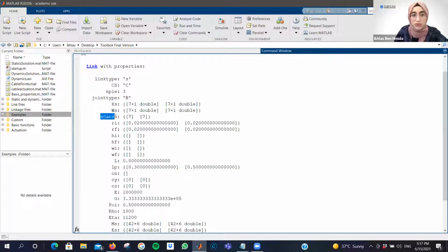The Gaussian points we've set, we used 5, but 2 points are added to each division. 1 point at 0 and 1 point at the end of the length, while the rest of the 5 points go from 0 to the length of the division. And so you can see that you have 7 points for the first division and 7 for the second one.